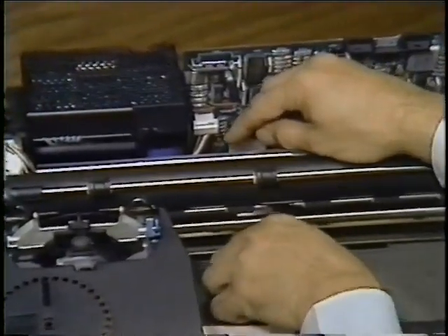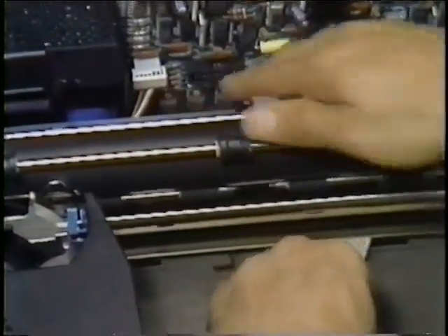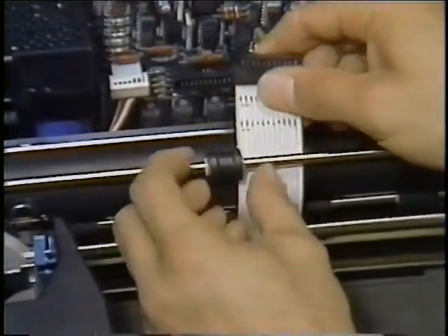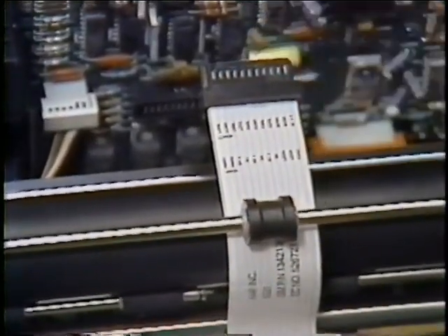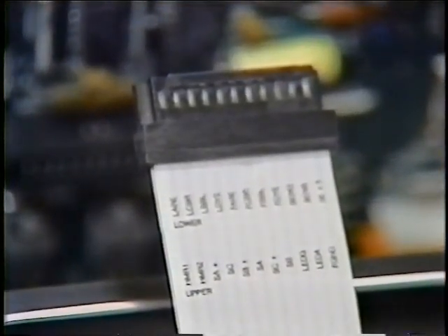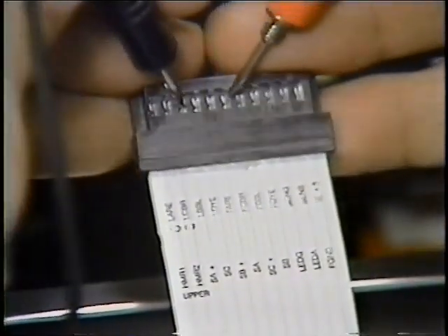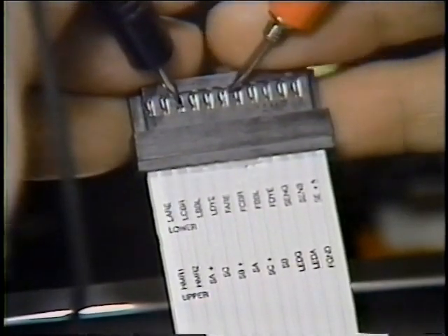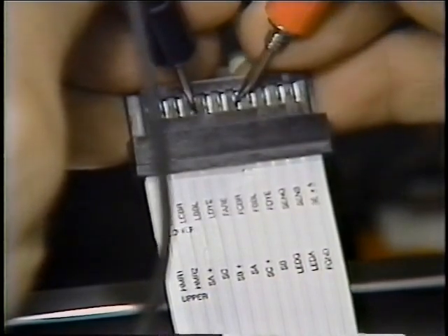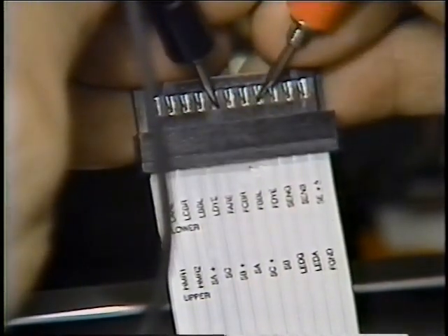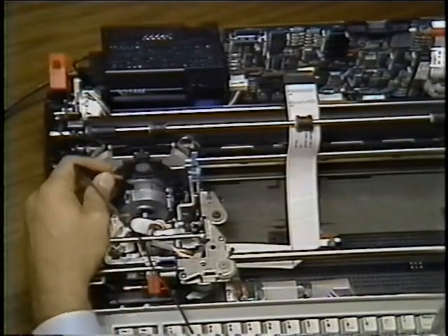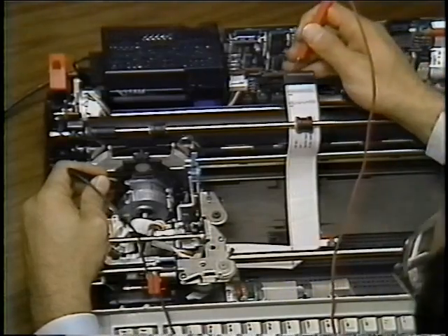The selection motor resistance check is done through the carrier cable. The selection motor signal names printed on the carrier cable show that the selection motor pins are on the top row of the carrier cable connector. To perform the resistance check of the selection motor, unplug the carrier cable, zero your meter, and measure from pin 3, which is SA+, to pin 6, which is SA. The resistance must be from 4 to 6 ohms. Check the resistance from pin 4 to pin 7, then from pin 5 to pin 8. Next, check to be sure there is no continuity between the motor housing and the selection motor pins on the carrier cable.